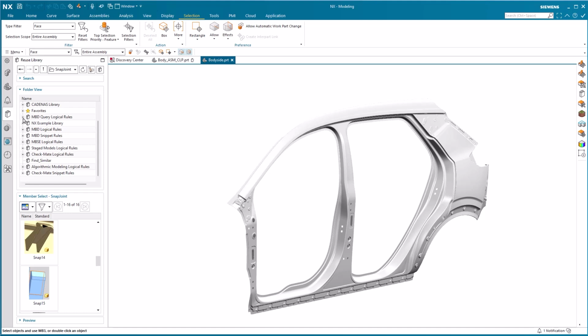And so I have created some of my own shape regions in a separate sub-library where I have write access. I navigate to the folder Find Similar, holding the shape regions I'm looking for. Here I can see that I have a square hole defined and in addition a support hole. To use this shape as input to my Select Similar Faces tool, I simply hover my cursor over the option in the member select area and right mouse button click on the required shape region.